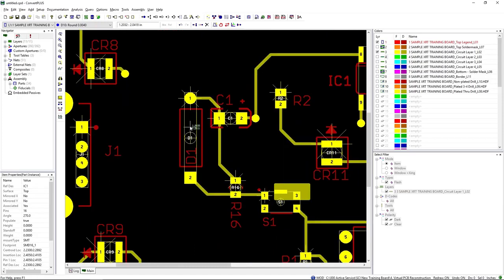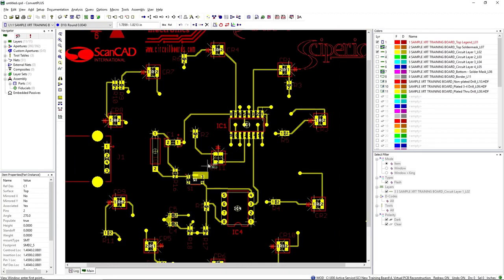Additionally, we can actually rotate any components just by right-clicking. So for instance, on this diode, I can right-click and, oh, actually that one only has one instance, so I can't rotate that diode. But what I can do is rotate something with multiple instances, like this capacitor. Come down and rotate it, and you'll see that it'll just flip the pins. So you have full control over how the pins are programmed, and again, you can see it's a very quick process.